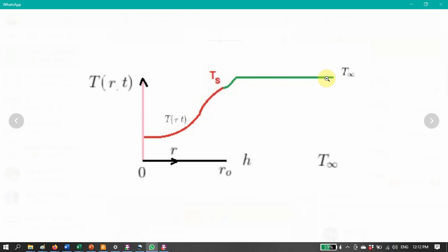the fluid. And then I also show you the one-dimensional model of the sphere that we use to model the egg. So we have an assumption here. When we model it as one-dimensional, it means that there is no temperature distribution in any angular direction, right? And then the heat transfer coefficient will be constant throughout the time. Also, the fluid temperature does not change with time.